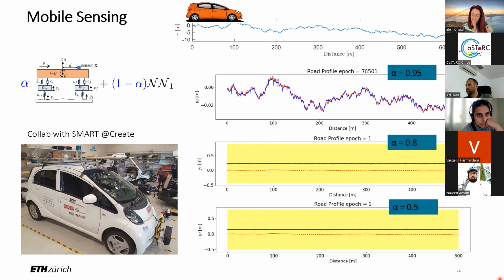It's not only good for the case where there might be some malfunctioning of the sensor. In fact, we also show that you can use this redundancy to infer an uncertainty quantification framework on the confidence of its sensor. How can you do that? You can adopt a leave one or leave k out sensors in the prediction, which gives you a way to actually also, through this redundant sensor that you keep as a test, quantify the level or the precision of your predictive capabilities by doing something like this. And you can use this logic also to get rid of a sensor when it's actually malfunctioning, in fact.